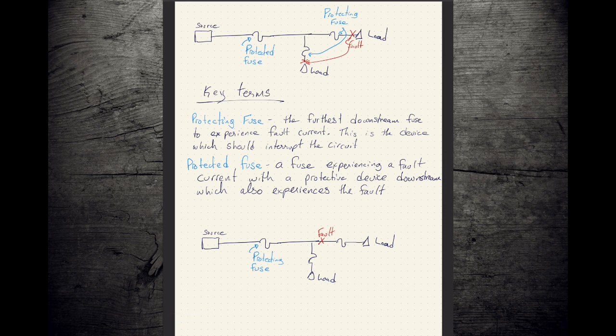So when we're talking about fuses or protective elements in series, I'm just going to call everything a fuse for the purpose of this argument and our lecture here today. So the idea of a protected fuse could be a protected recloser or a protected breaker, but we're just going to go with fuse for the sake of simplifying the discussion. So we introduced the concept of a protecting versus a protected device. The protecting fuse is the one you want to operate.